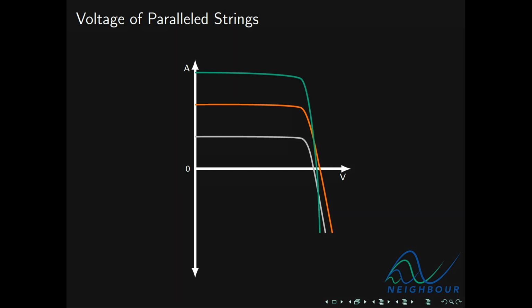And to find their settling point, all we have to do is flip one IV curve. In this example, I just flipped the shaded one, but I could have flipped the non-shaded one, because once I flip them, I'm going to get a point of intersection where their currents are equal but opposite in magnitude. And that is exactly what's going to happen. They're going to share a current, and that current value will correspond to their combined output's open circuit voltage.